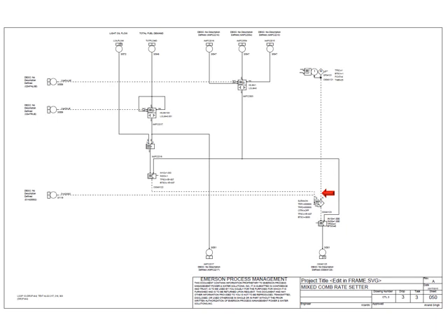Take note that we are trying to analyze the whole control sheet. That's why we are identifying each and every function. But if you are tracing a signal or trying to understand, let's say, a control loop, you don't have to do this. Just focus on a particular signal, where it came from, where it went, and how it acquired that value, considering the current conditions.